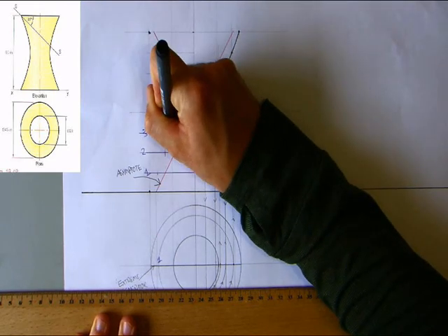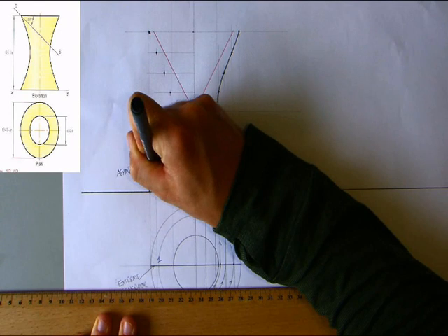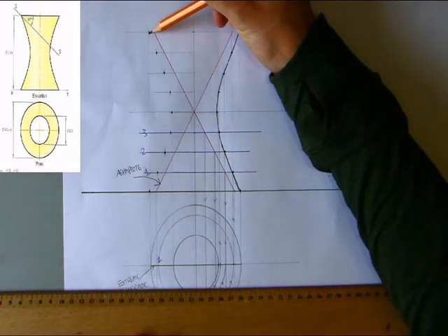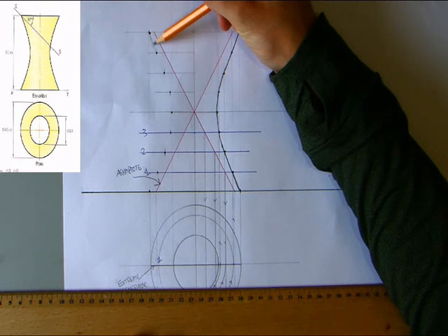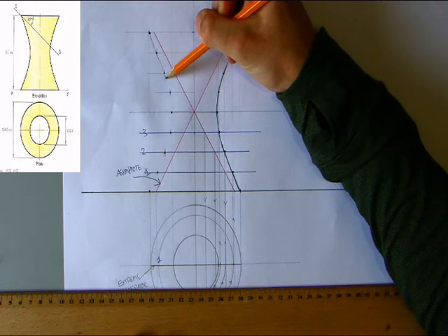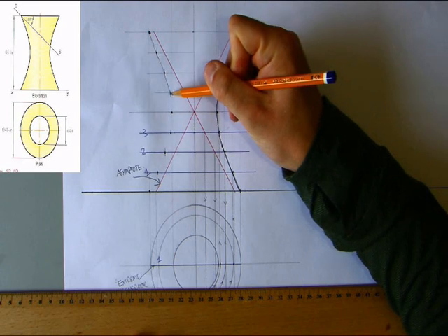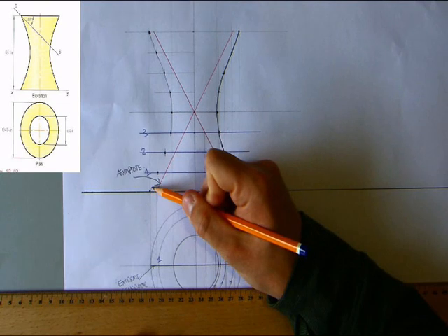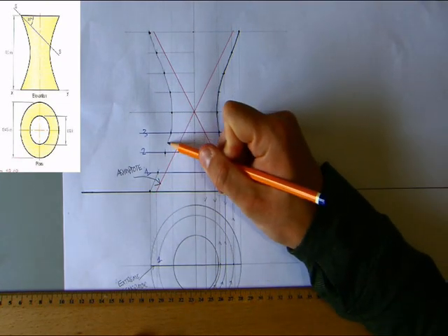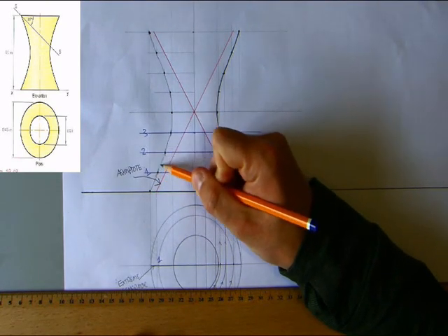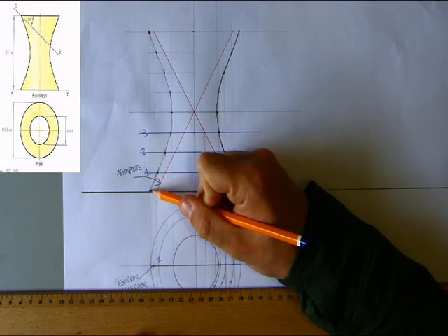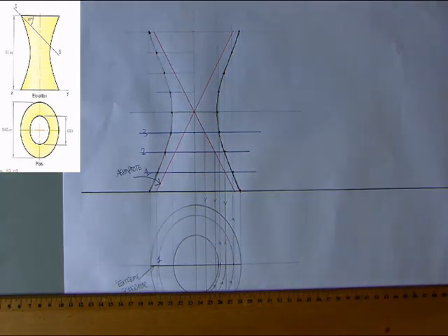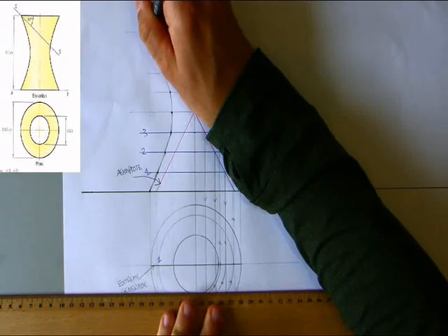If you don't think that's enough points to get your accurate curve, what you need to do then is do a few more cuts using the same technique to get an accurate curve. It is important to communicate a nice accurate curve, and if you have a flexi curve, this would be a great time to use one now. Okay. Again, going over this.